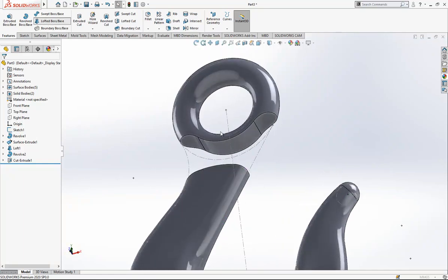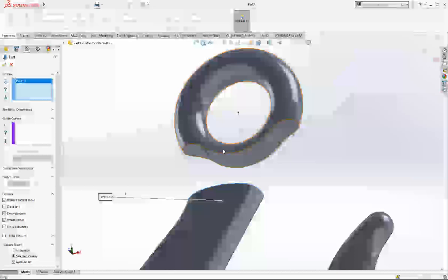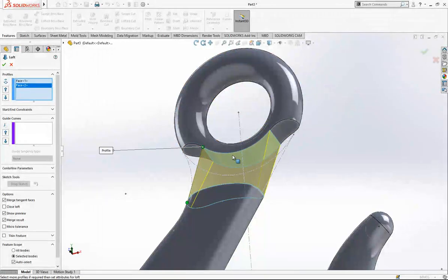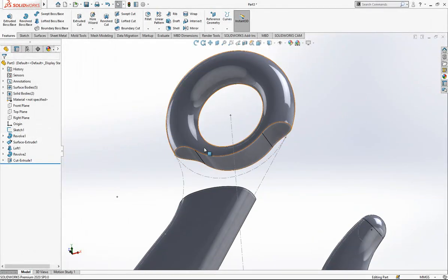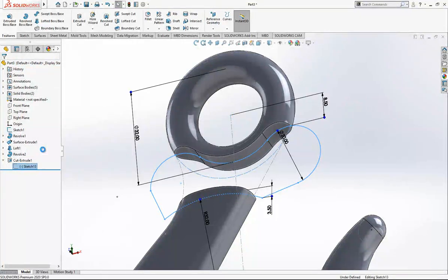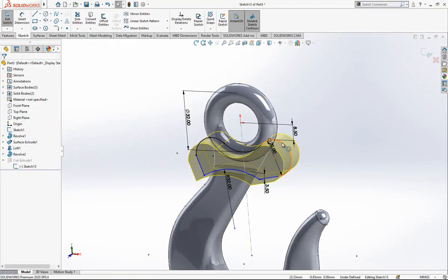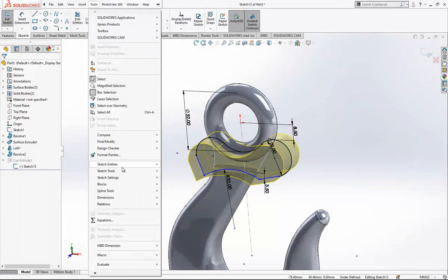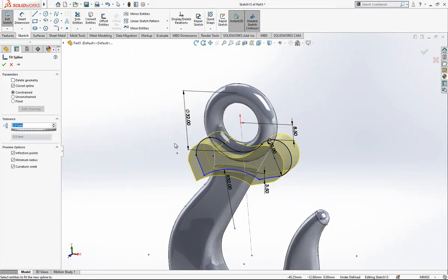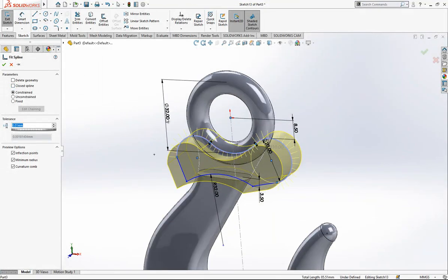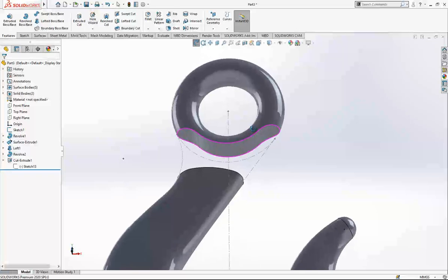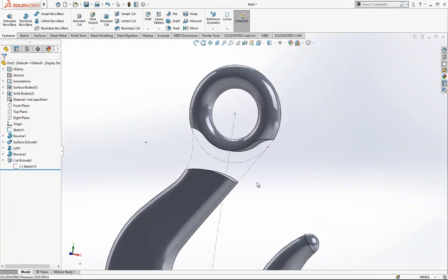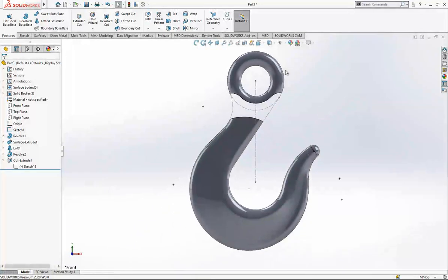I want to make a loft surface between this and this area, but because I'm not able to pick 3 different surfaces, now I should remove these 2 connection points on my sketch. How are we doing that? With spline tools, with spline. It will not be a closed spline. This one, and this one will be converted as spline. And then we are going to cut our surface. As you see here, we don't have any connection now. That was one important thing.